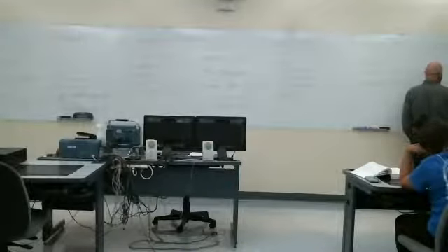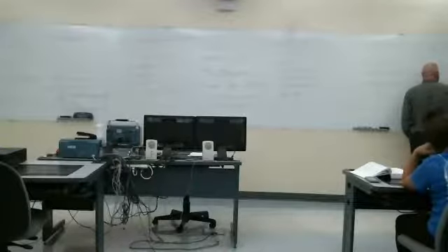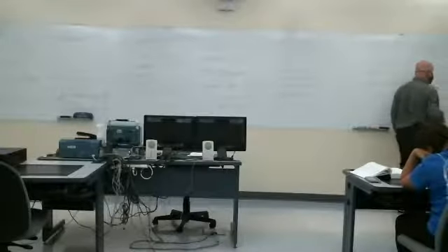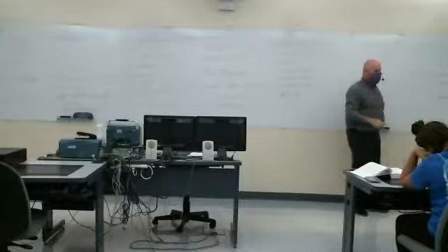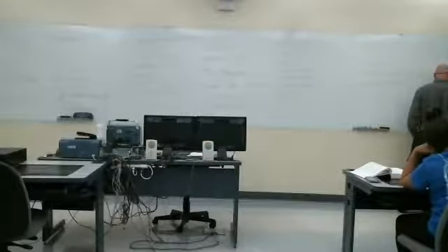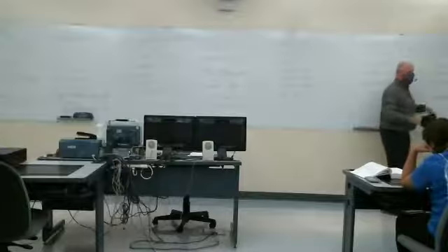Over here, what's the delayed output look like? This is y of t minus delta. I go back to my original y of t expression and I substitute t minus delta in for t everywhere, and it's t minus delta x of t minus delta. Okay, so this is kind of the mathematical proof that these are different.